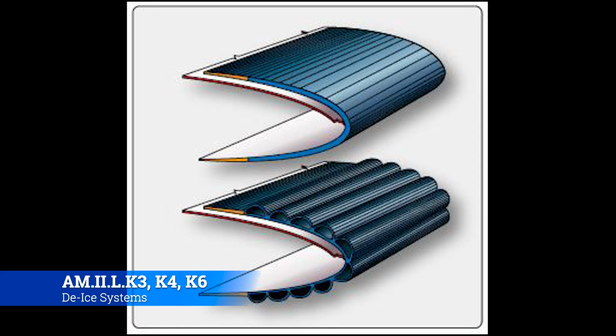Now, there's a couple of different styles of boots that you'll see out there. This is one that I'm most familiar with. You'll see them on King Airs, where different valves will open and close to inflate different parts of the boots. So effectively, on that bottom picture, you'll see one row inflate and the other one deflate, and then they'll reverse it. And what that will do is keep the ice from sticking to the leading edge of that wing, because it's basically pushing it off every couple of seconds.